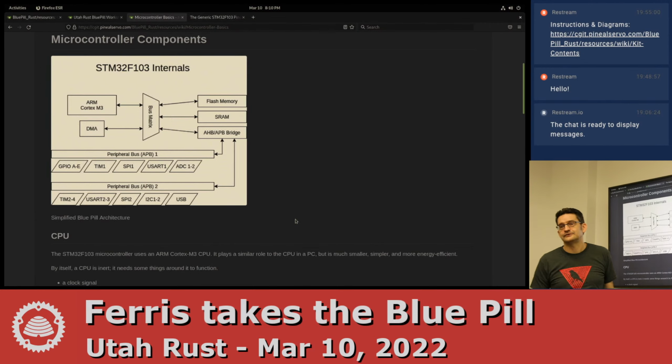There are a lot of times when you need to move a bunch of data from one part of the address space to another, and you can either run a memcopy command, a loop that occupies the CPU doing all that, but the DMA controller is basically a hardware memcopy loop. You program a source, a target and a size and say go, and it'll do it.